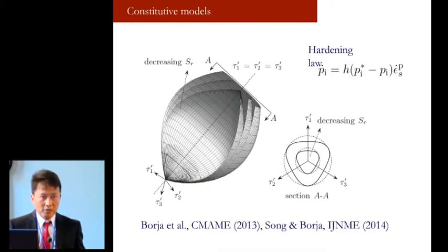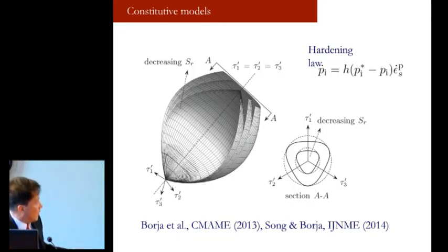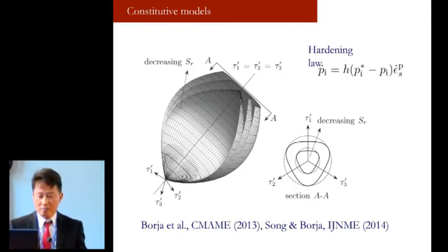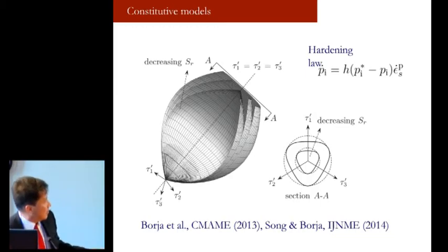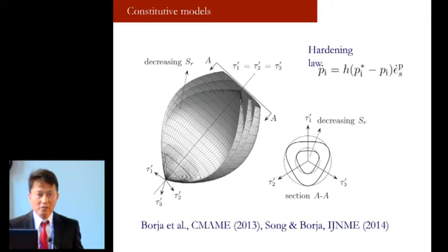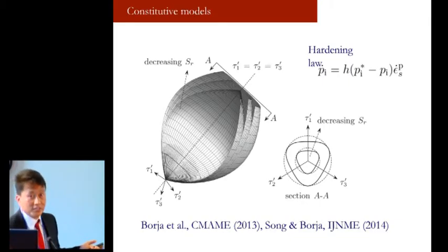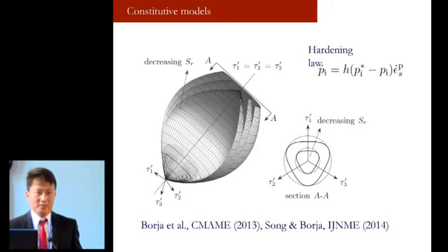Now, the constitutive model for the solid matrix is something that is quite tricky to implement, considering that we anticipate very complicated constitutive laws or properties for the solid. So in this particular simulation, at least, we implemented a variant of critical state soil mechanics, where we implemented a three-invariant model. And we have here a number of yield surfaces that vary with respect to the suction stress. So this is a single porosity formulation with a single yield surface, except for the fact that the yield surface varies with the suction stress.